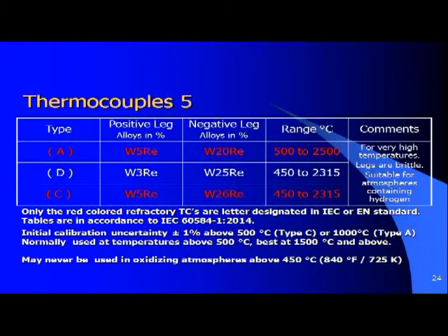The two thermocouple combinations highlighted in red are now newly in the IEC 60584. So they can be used for type A and type C. By nomination, the positive leg has the same alloy combination, but practically you cannot interchange them.